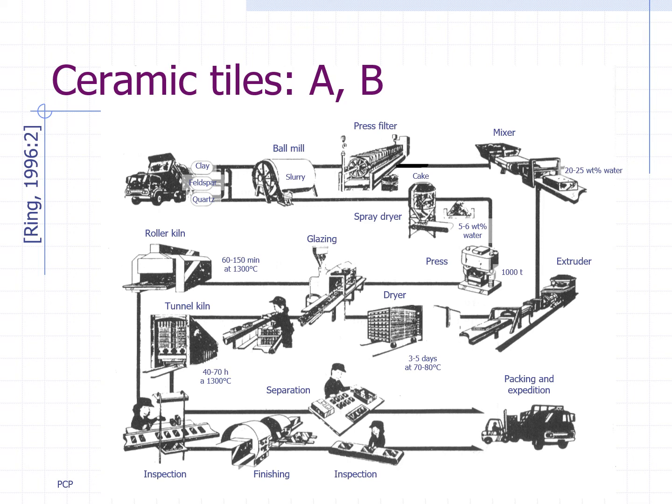The paste is conducted through an extruder to give it a shape. In the sequence, this green body is dried, eventually glazed, and set into a tunnel kiln. Traditional kilns such as this one used to take 2 to 3 days at 1,300 degrees C to complete a firing session.